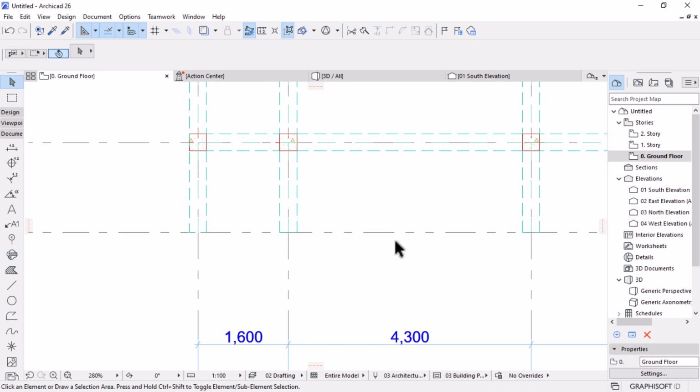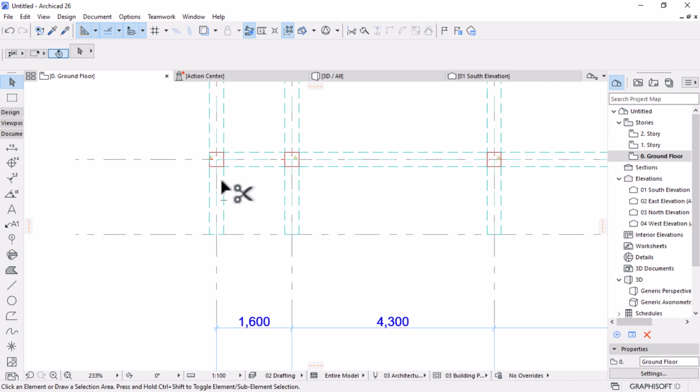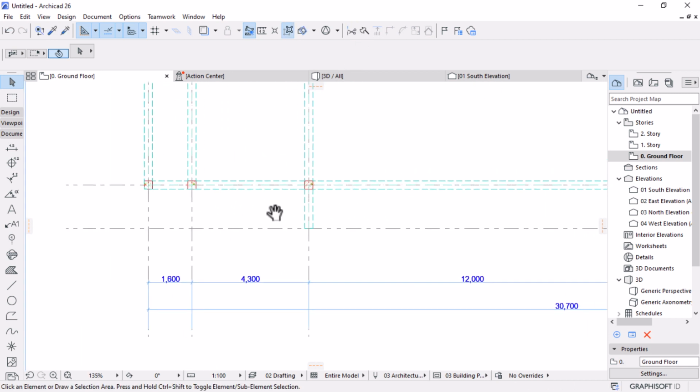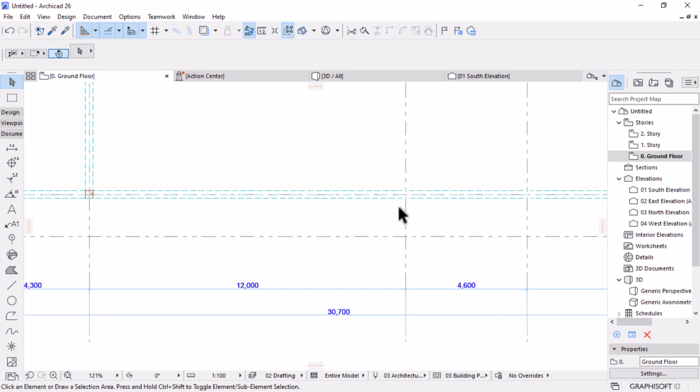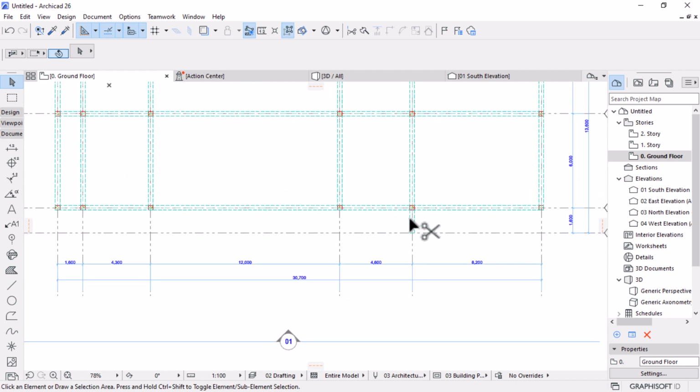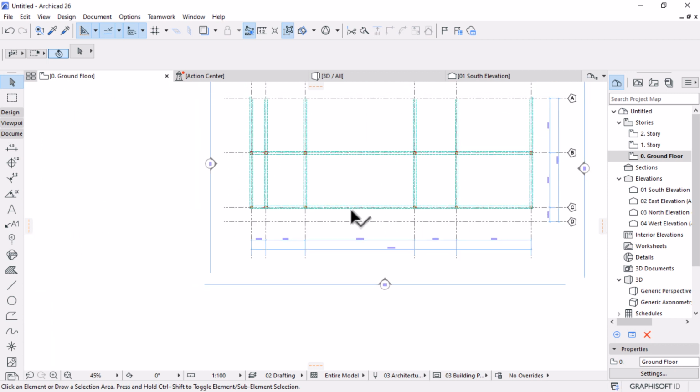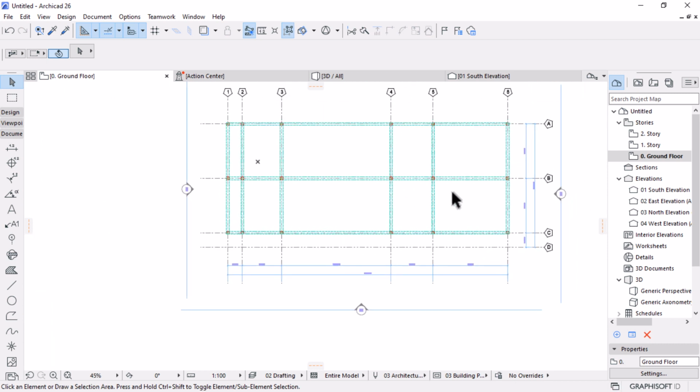All these columns I have to go, and then I would activate the trim tool, or just come here. The reason why I'm using the shortcut is continuous, but for this tool you have to trim one element, then you go back there, trim another. This will take time. So if you use Control Hold, you could just continuously trim your elements without going back to the tools many times. Okay, what happened?